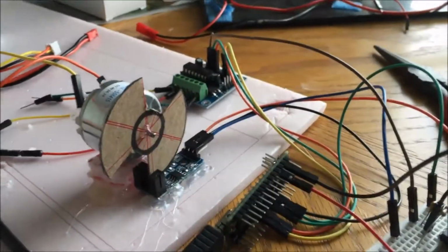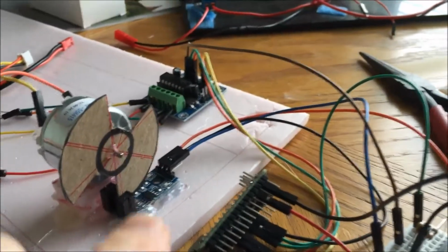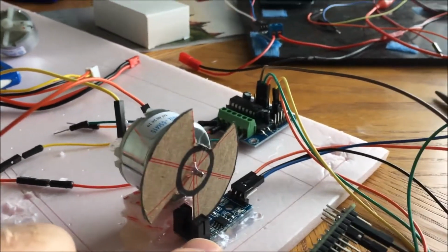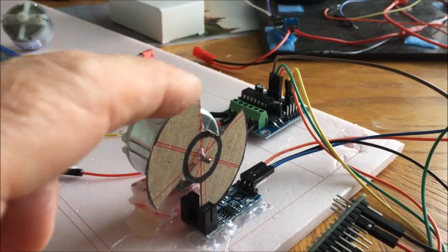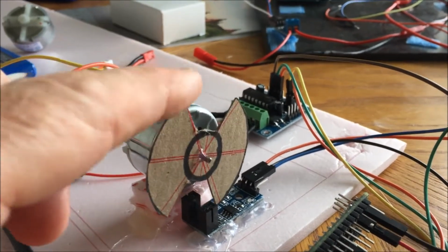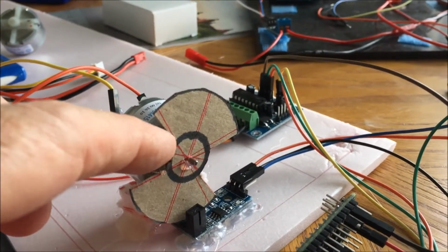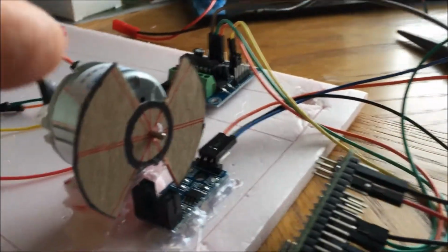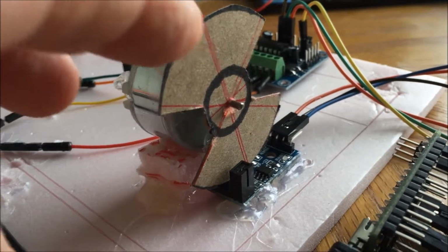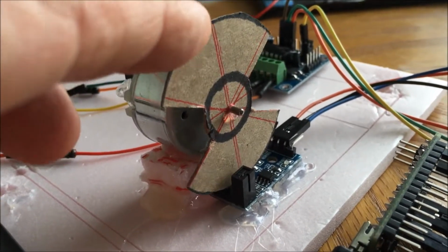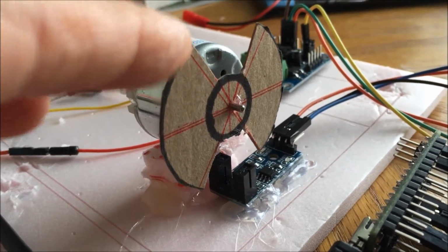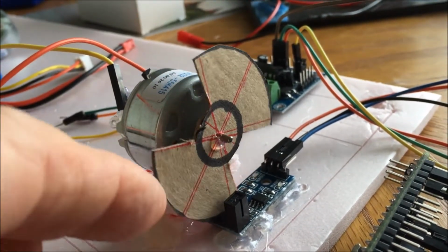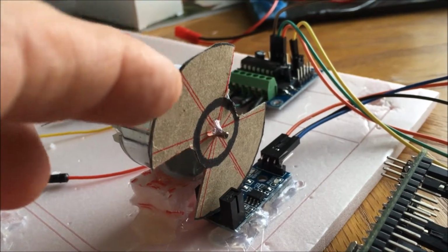At the end of the last video, I was using an optical sensor to try to measure the RPMs of a DC motor. What I had done was put a cardboard disc onto the shaft of the DC motor with two slots cut out. And this should lead to two rising edges. So when the cardboard interrupts the optical sensor, I get 5 volts as the output, and when it's open, I get 0 volts. So this should lead to 2 rising edges and 2 falling edges during each cycle of the disc.